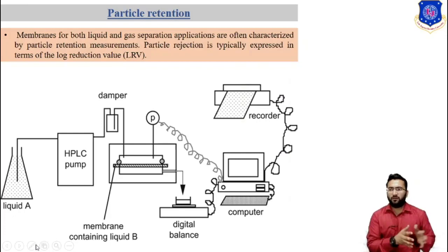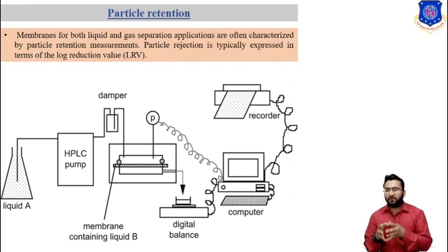The challenge level may be dilute, 10^8 to 10^10 particles per liter, or concentrated, 10^13 to 10^15 particles per liter. Both monodisperse and polydisperse particles are used. The instrumentation is typically laser particle sensing and counting with automated data collection and analysis.